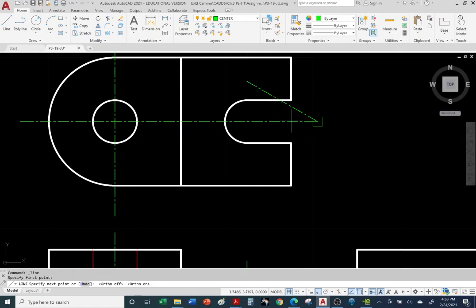But it's still going to try and snap. Okay, so it will allow you to snap. So be aware of that. It's two options that are fighting each other. You have ortho and snap fighting each other, and that's why the line is disappearing and reappearing. Okay, and click and hit escape. All right, so that is ortho mode.